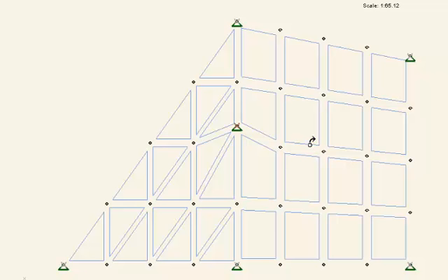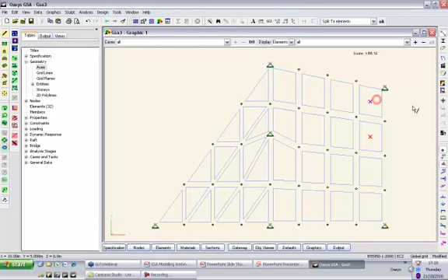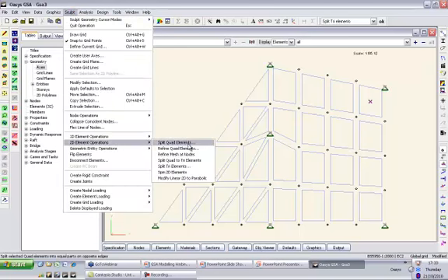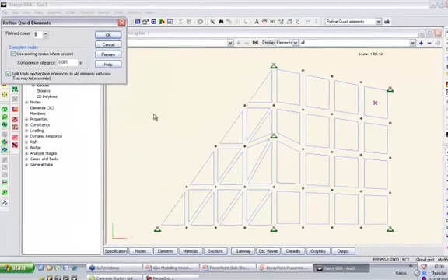For those of you who've done 2D element analysis, you'll know that where you have support points, you get some very high stress concentrations. And what you need to do is reduce the size of the element local to that point. So if I put it here, big elements are okay in the middle, small elements you need around the edge. And so we have a refine quad element command, which refines at a corner.